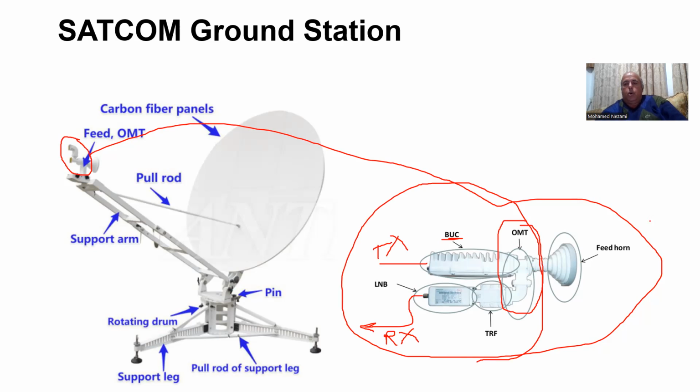So we've got a circularly polarized signal that comes in here that has vertical and horizontal. One of these will be a received signal that will come in here and go to the LNB, the low noise block, and gets received without receiving the other one, completely eliminating the other one, and vice versa.